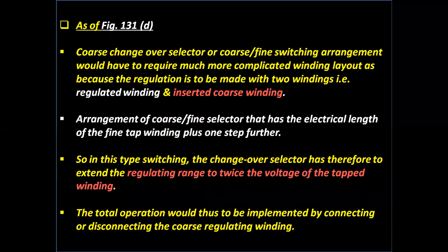As in figure 131D, the coarse changeover selector or coarse fine switching arrangement requires a much more complicated winding layout, because the regulation is made with 2 windings, that is regulated winding and inserted coarse winding.